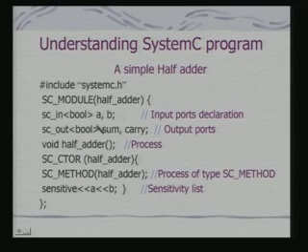So, here we are defining a module which is a half adder. Okay. Now, these are input ports, Boolean ports, let us say A and B, then output ports, they are also Boolean, sum and carry, and in fact, you also have support for data types. A programmer can use the data types, and there are also hardware specific data types which can be used in your program.